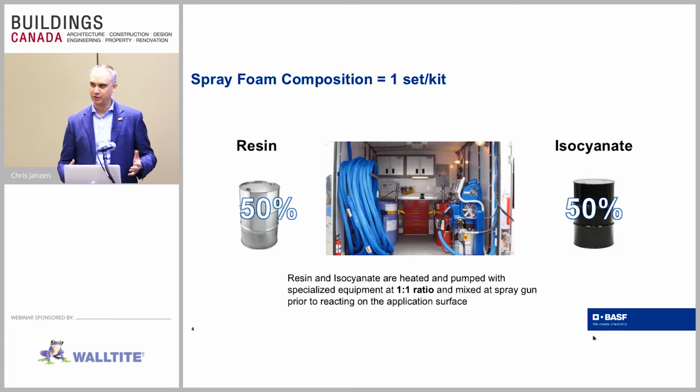So these types of applications, the issue with it is you don't know what's in that stud cavity if you're just shooting foam in there blindly and you're pulling a trigger. So you don't know, are you actually filling that stud cavity with insulation? Are you leaving voids? What's happening with the vapor barrier properties, the air barrier properties, because you can't see what's going on in there. So if you're going to use spray foam, any kind of retrofit type of stuff, you want to make sure you're taking the drywall off so you can see what's going on inside that stud cavity.